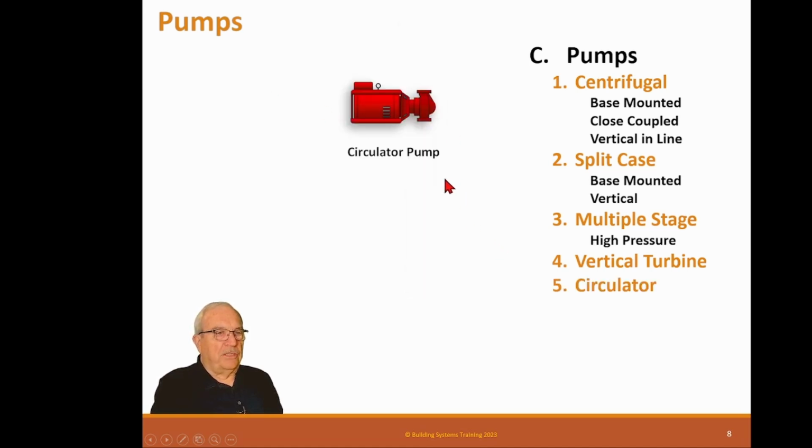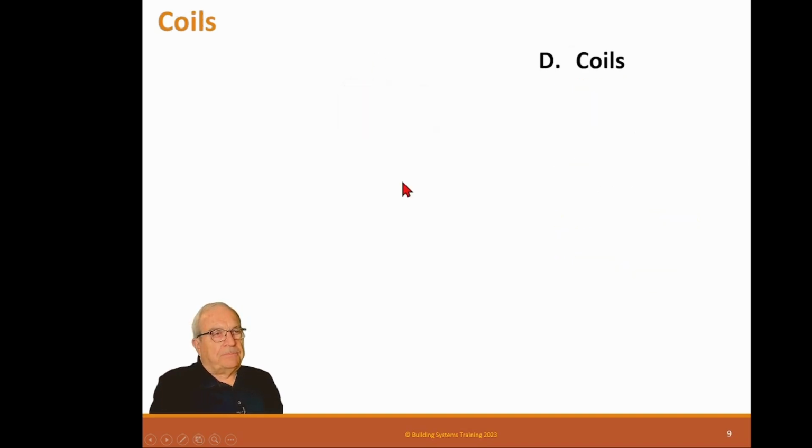Then we have circulator pumps. Circulator pumps are designed for domestic hot water systems or really small flows, and these are inline in a pipeline with a small motor. These are normally between 1/2 inch and 3-inch. Nowadays they are making some big ones that sit vertical, and you can get big pumps. The problem with these is the mountings are always complex because the pipe supports some of it, but if you have a big motor, the best practice is to support the motor separately.